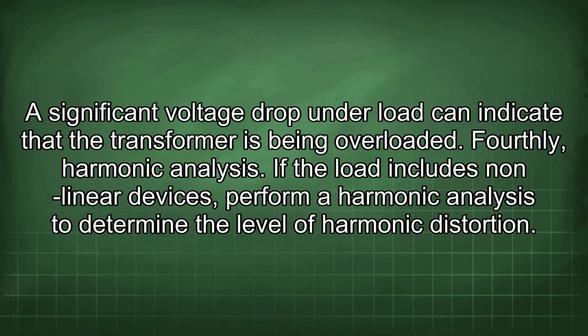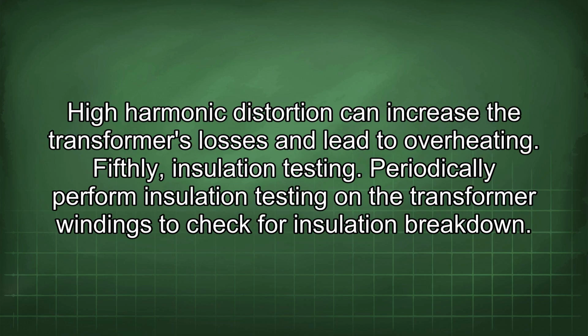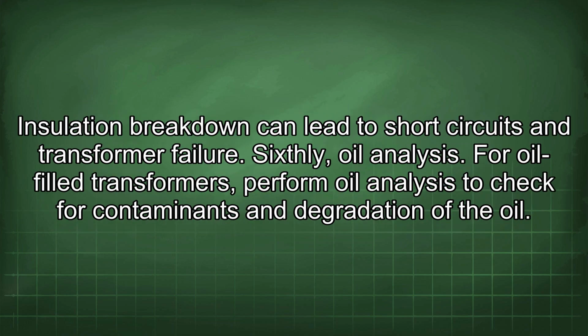Fourthly, harmonic analysis. If the load includes nonlinear devices, perform a harmonic analysis to determine the level of harmonic distortion. High harmonic distortion can increase the transformer's losses and lead to overheating. Fifthly, insulation testing. Periodically perform insulation testing on the transformer windings to check for insulation breakdown. Insulation breakdown can lead to short circuits and transformer failure.